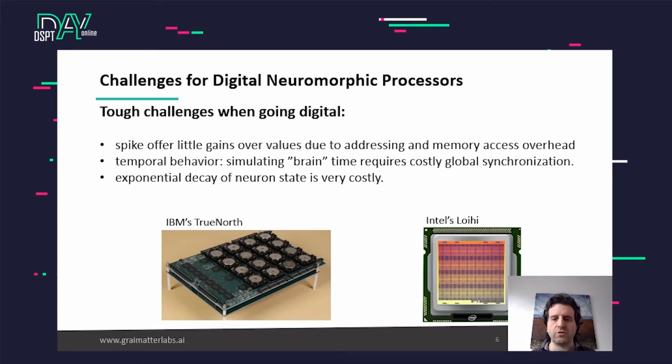If you talk with a neuromorphic engineer, very often they will suggest to you that spikes are going to make your execution a lot more power efficient, because if you do your computation only using spikes, only sending ones and zeros, what's going to happen at the side of the receiver is that when you multiply by the weight of your synapse, this multiplication is just a multiplication by one, so you can remove that multiplication, and instead the only operation that you do is an addition to the potential of the receiving neuron.